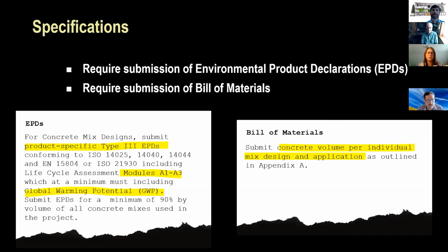One thing that I wanted to note here, and it's highlighted in the EPD text there, is that MKA is asking for 30, and that's kind of a stance that we've decided to take internally. If you look at the LEED credit, the declarations, they give multiple different tiers, I guess, of EPDs you're allowed to submit, and we recognize that. But for us, we've decided that we want product-specific Type 3 EPDs, which means third-party verified too.